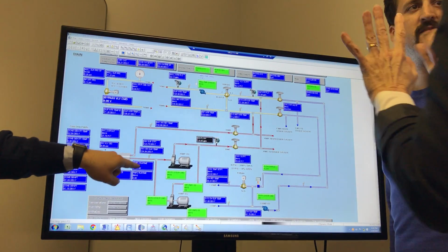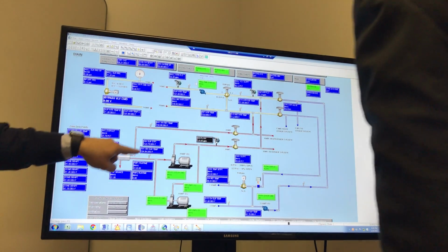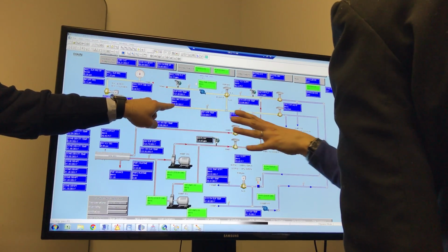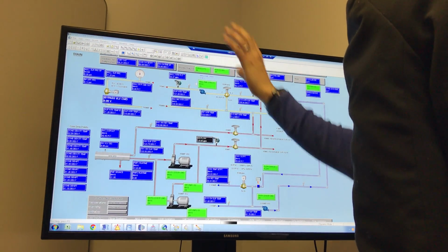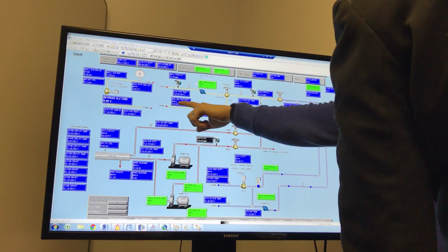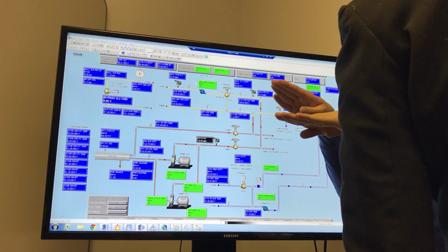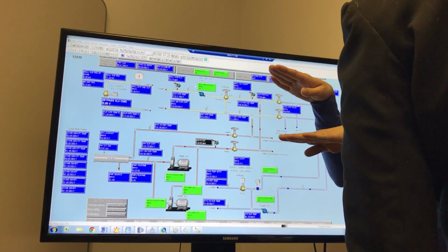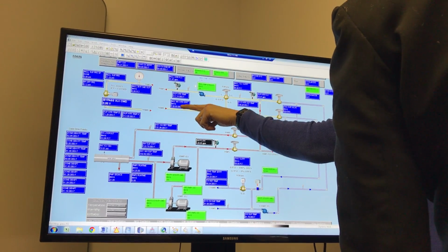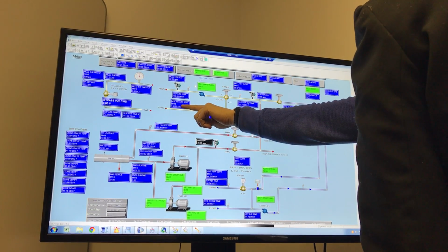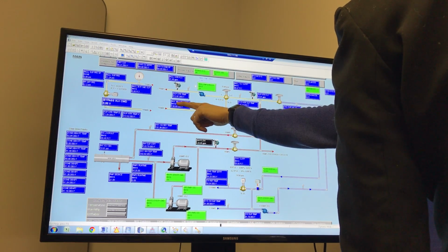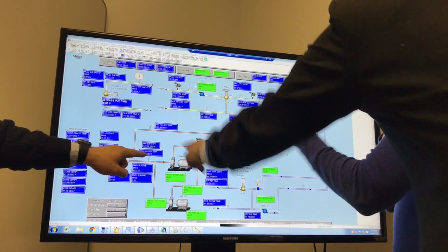Wait a minute, it takes around 5 minutes. It cannot run the whole loop in 5 minutes. But this is the maximum temperature we can get from the basement, so we will never go there. In fact, there are 3 PID loops. One measures what's my set point, one what's my average temperature. If the error increases, it controls this one and makes this as high as possible with a limit of 140. That's where we don't want people to touch and get burned. Right, okay, so the limit is 140.